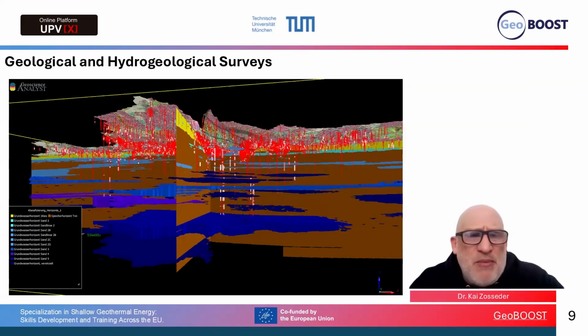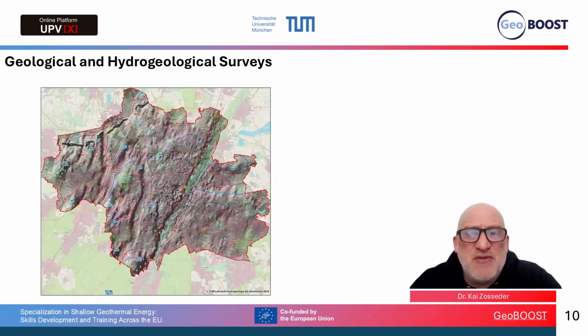So we have here a complex 3D model. The red lines are the drillings and the boreholes, and the white parts here are filter sections that we defined here, and the blue bodies are the groundwater bodies that we assessed here in a 3D model. So it can be quite complex, but it can also be described by cross sections and borehole interpretations at a specific location, of course. So here's an example of such a relief of an aquifer. You see some channels and some plateaus as we described before.